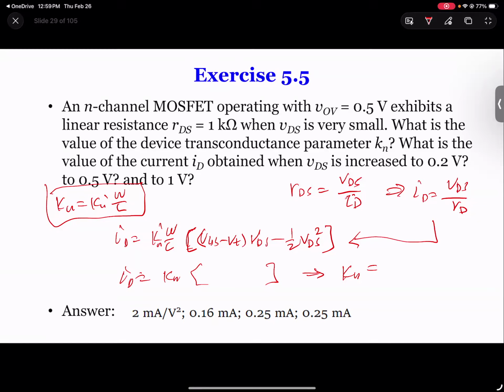The trick is that for MOSFET, there's a square here, and in the saturation region you also have a square, VOV squared, right? That square makes our problem much more complex because you always get 2 solutions, and only one solution is correct, the other is wrong. That's the difficult part. When we get to BJT, we're not going to have this type of issue. Okay.